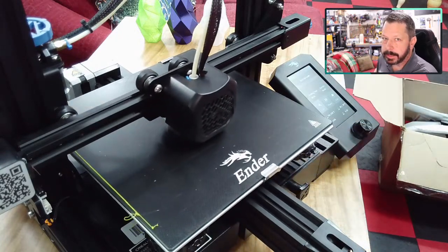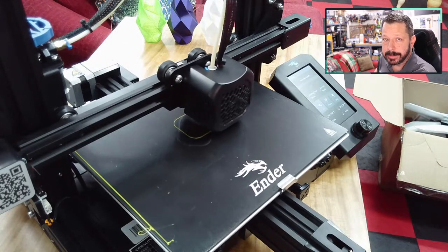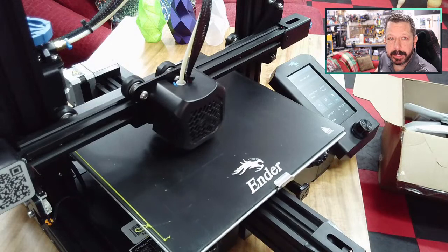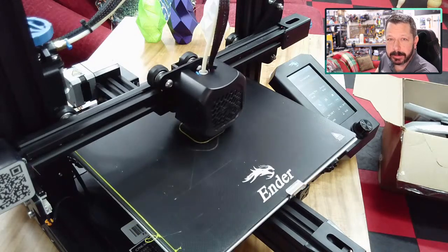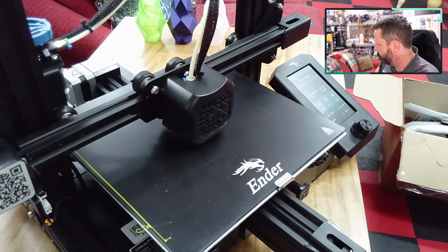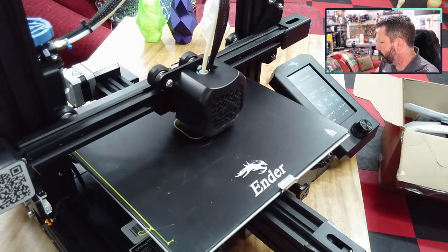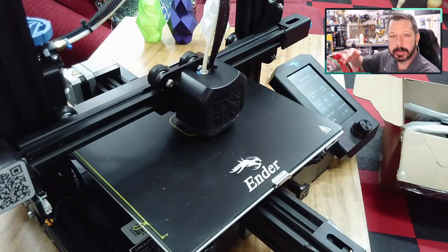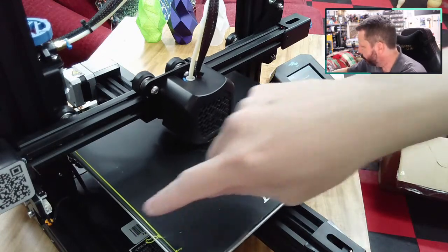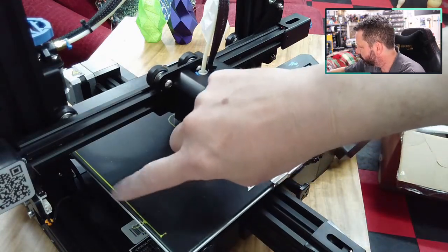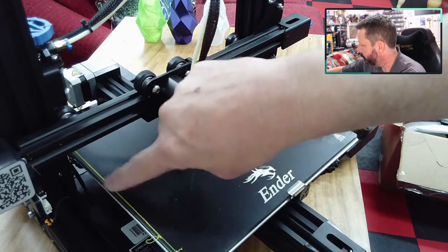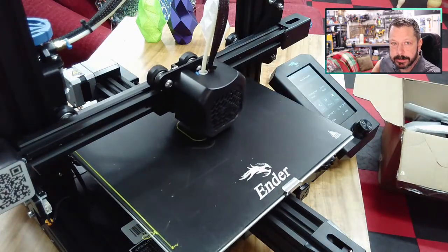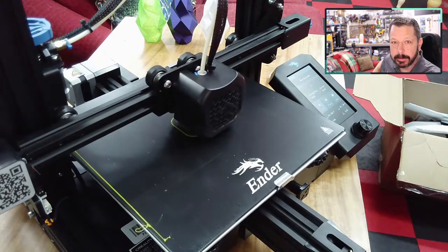If it's squished completely flat on the bed, it will stick, but you're going to have that elephant's foot at the bottom. Now this part, it won't really matter because we're not measuring the bottom anyway, but you do want a little bit, like I'm rubbing my finger across there, you want to be able to feel a hump of filament, and you don't want the filament to come loose. So that looks like a pretty good stick, but not being so squished that it's going to create elephant's foot or removal problems.